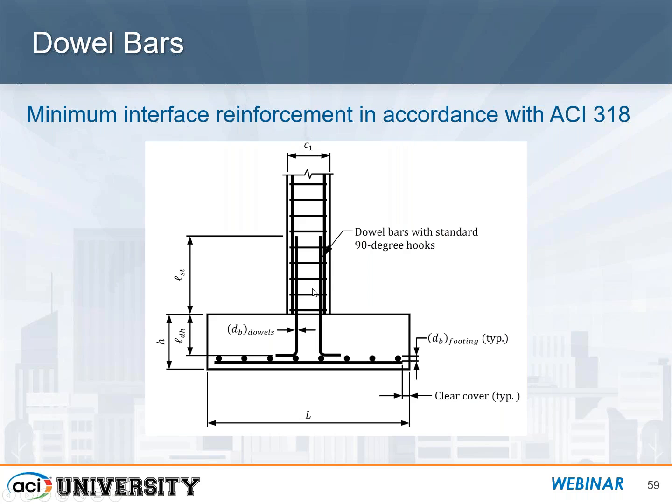If the vertical element is subjected to just compression, then we can lap splice the bars in, say, the column with the dowel bars for compression and provide a compression development length. We would carry the dowel bars down to the level of where the footing reinforcement is and tie it. And if it's in compression, we need to develop it in compression, not counting on the length over which the hook acts. ACI 318 does not recognize the hook length with the bend diameter as part of your development length.